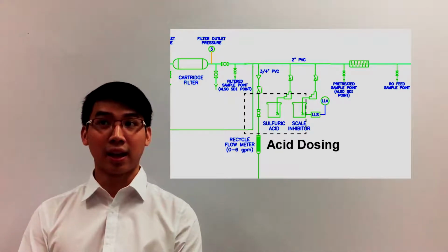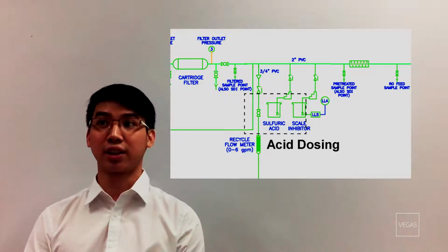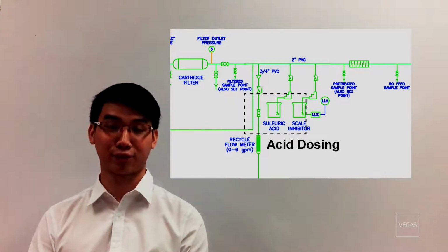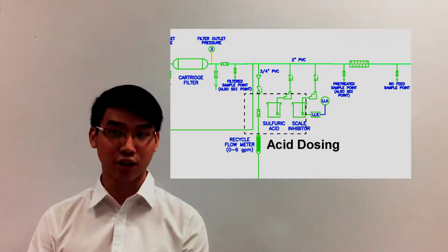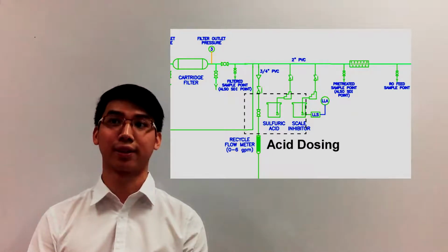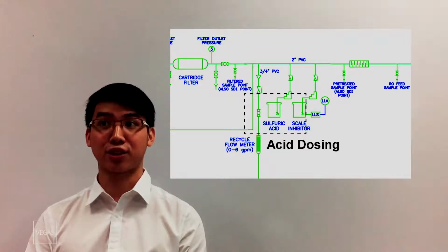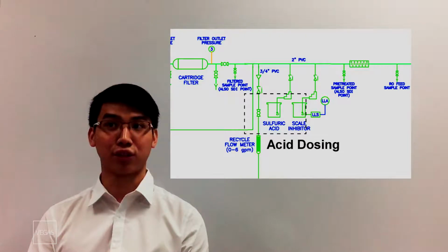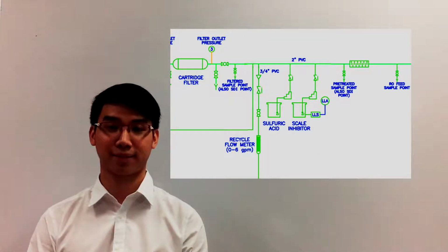Apart from that, an LMI chemical dosing pump is also inserted in the effluent stream coming out of the cartridge filters. The pump is used to control the pH of the water in the range between 6.5 and 7. In a nutshell, the exit stream from the cartridge filter will go through the anti-scalant and pH conditioning before entering the RO stage for separation.